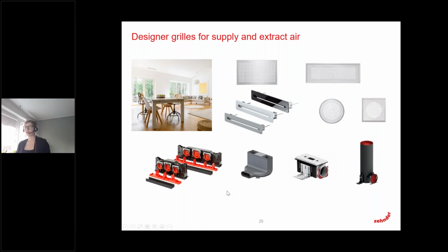Yes, and when the air volume is important, and with, let's say, one tube it's not possible to reach the level that you would want to have, then for ComfoGrid Linea it's possible to connect two tubes. So in that way, we can have one outlet with up to 90 cubic meters per hour air volume. This is quite commonly used for living rooms or dining areas.